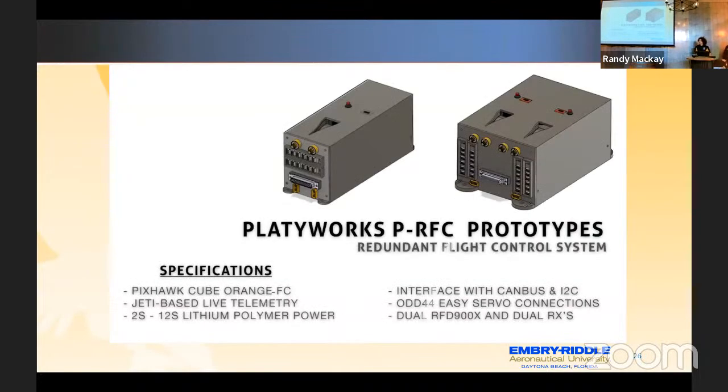So to provide some clarification on the video, with the RV8, the initial roll maneuvers was just testing primary to backup switchover, and the backup kill switching the primary. With the severe upset recoveries, that was me putting it in the worst possible case scenario, essentially deep stall, cover and maneuver, and the backup did the switchover, took it over. I had no input into that. And then once it proved that it was reliable, that's when I switched to the Shock Cubs.